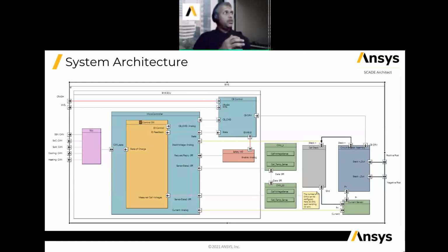So I have my microcontroller, my control software, my battery connection and disconnection arrangement, and safety mechanisms. All of those are implemented here in my architecture. And I will be able to explain what information I'm going to receive from the environment, which could be whether the battery is connected to the load or to the charging circuitry, what current is being drained from the battery, what the temperature of the battery pack is, and so on. There are many other parameters that I need to receive here to specifically understand how I should control the battery in the electric vehicle.